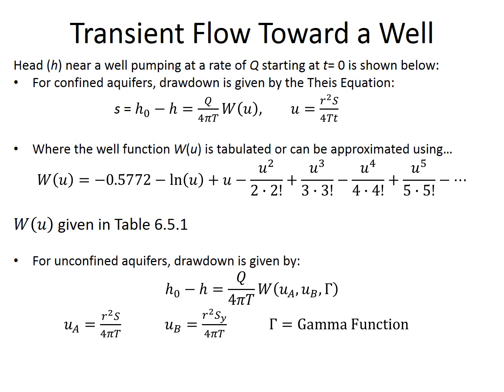I wanted to provide a brief summary of how we use pumping test data in order to estimate aquifer parameters at depth. We previously discussed the partial differential equation associated with transient flow, and you'll recall that we had both storativity and transmissivity as constants or parameters of our differential equation, and it is in fact the solution to this differential equation that we're going to be using in order to estimate those parameters, transmissivity and storativity.